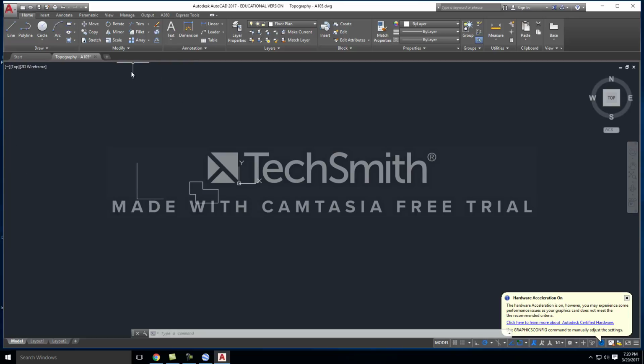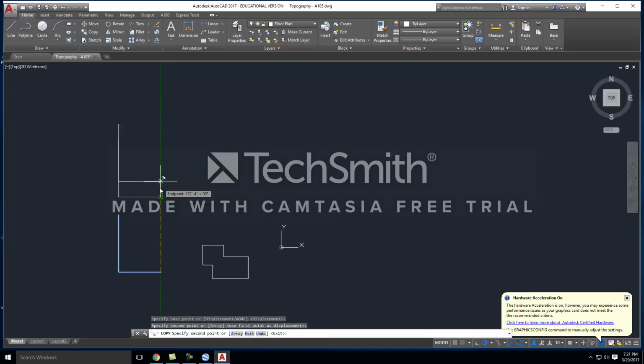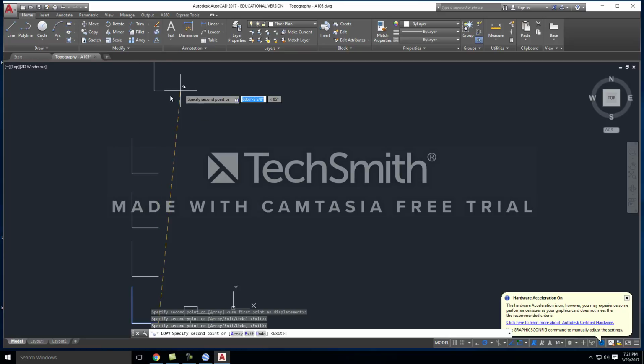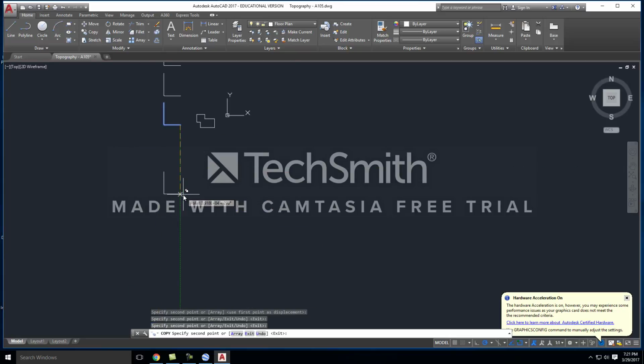Another one that you'll use a lot is copy. You click on copy, and just like rotation, you're going to specify a base point from where you're copying to and from, and you simply click on that, and you can copy that object as many times as you want. You can also just type in the distance that you want it to copy. So I can do something like 100 feet.